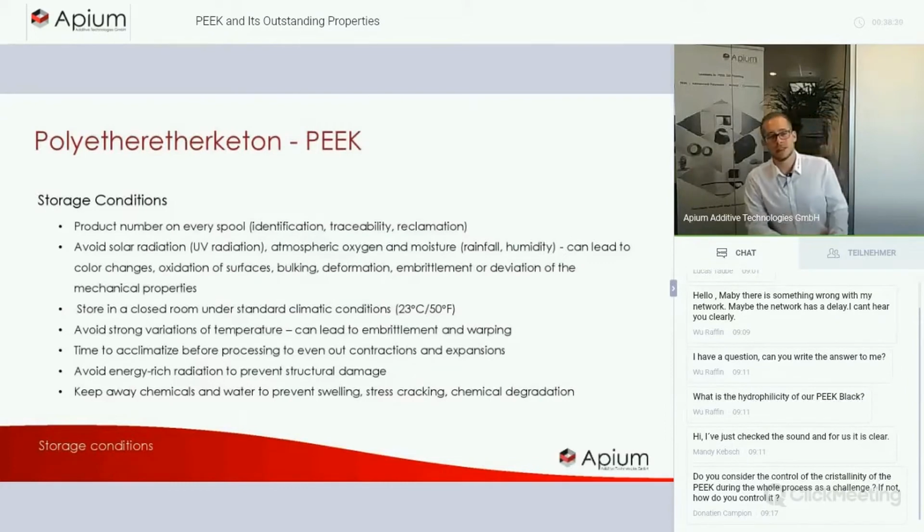The last point I want to tell you about is the storage conditions. So this is something very critical because PEEK is in nature hygroscopic. It tends to attach water on the surface. I think this is normal for most of the polymers, and therefore you need to make sure that the material is always in a dried state.